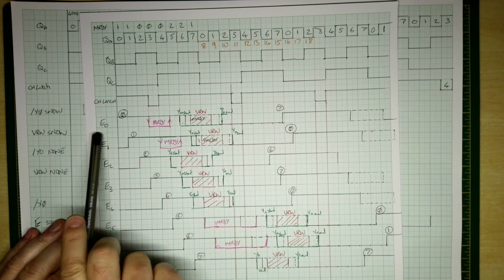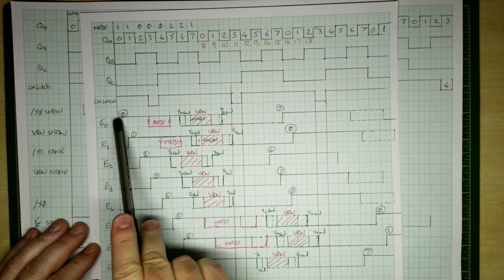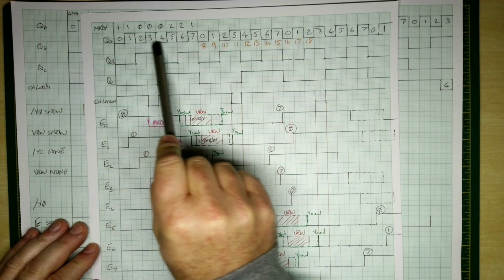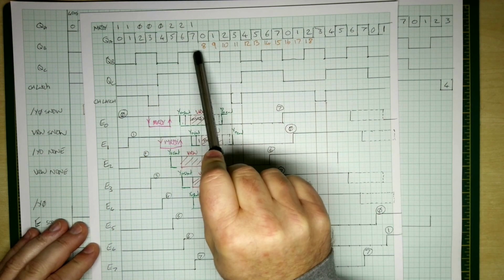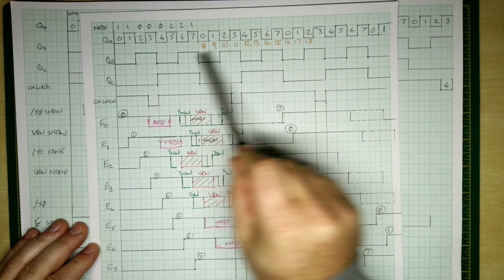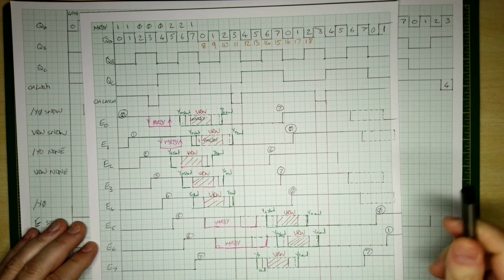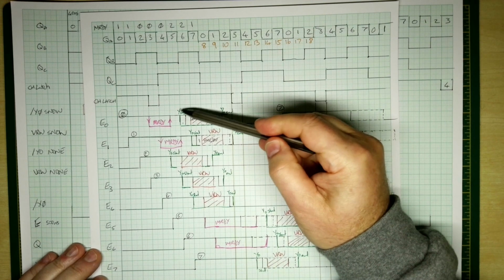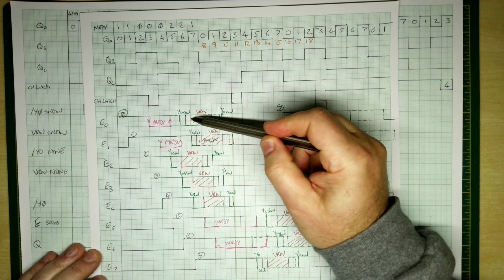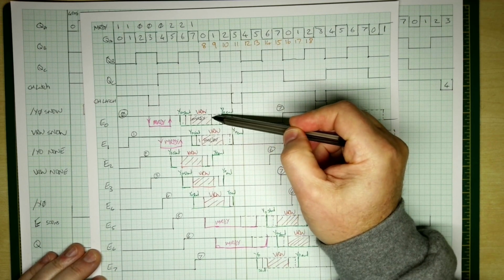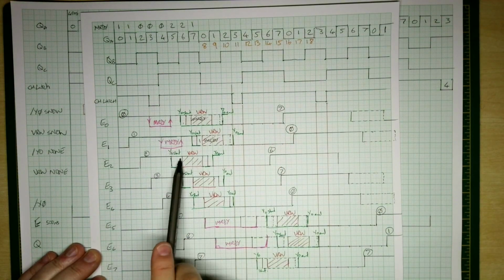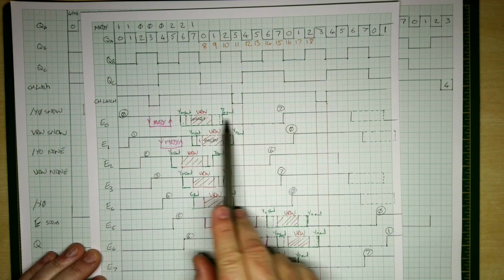So this was basically taking the E clock signal starting from 0, 1, 2, 3, 4, 5, 6, 7, and then counting these cycles all the way up to about 15, 16, 18. And what I was doing here really is to try and work out, is there a way we can codify where we want these various signals to start. So what I've got here is the Y0 start, Y0 end, and when the video read write starts and video read write ends. And then if we need to include the memory ready signal to extend the clock.